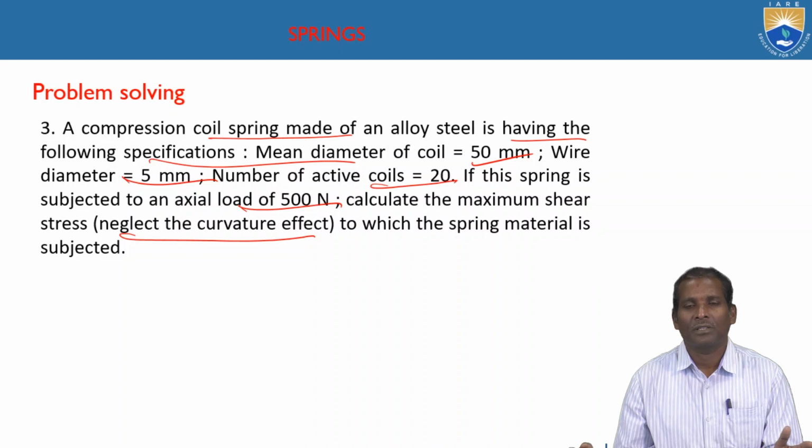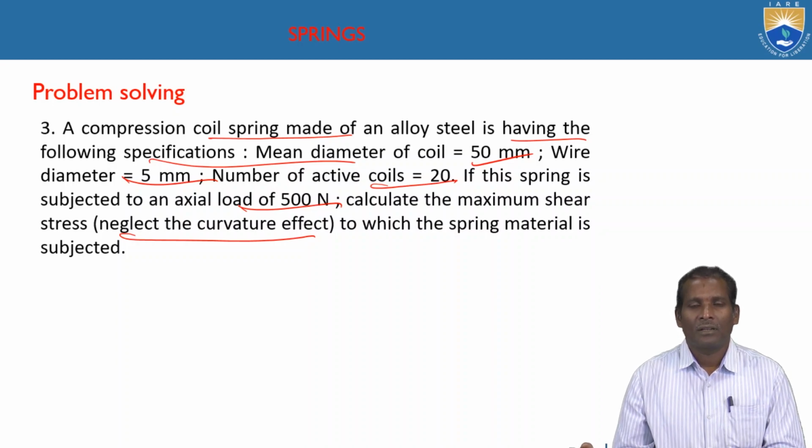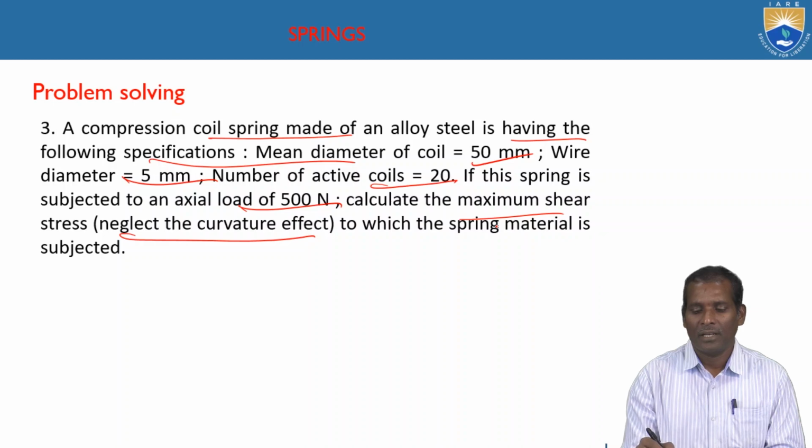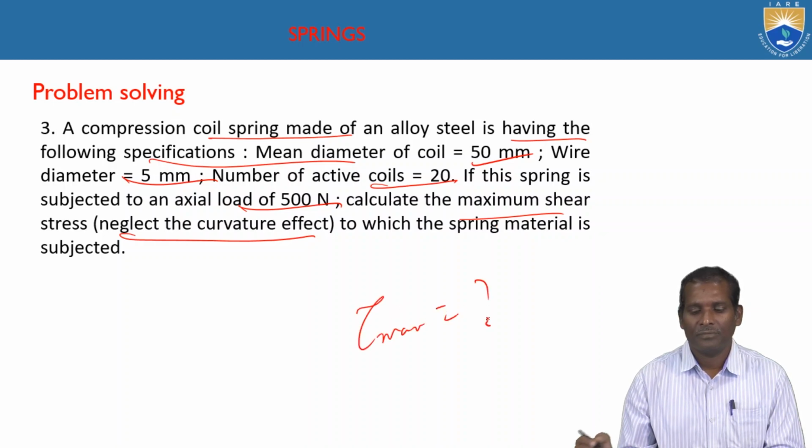Here we neglect the curvature effect, so only one shear stress is available, the direct shear stress, to which the spring material is subjected. So first write the given data, then apply the formulas and calculate the maximum shear stress.